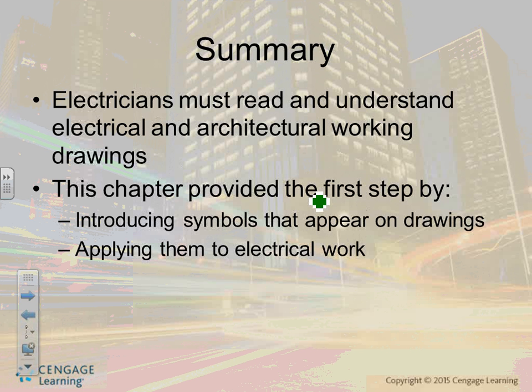All right, on page 39, my friends, luminaire lighting fixture schedule. Here's the symbol that they use for the fixture schedule. I would like you guys to look at this one. It says emergency battery unit with luminaire heads. So when they ask you where are the emergency lights in the building, make sure you look here. This is the symbol that they use. Typical. You guys are going to be using it in Revit too. Wherever you see the symbol, they call them bug eyes, guys, the bug eyes that are going right through the building.